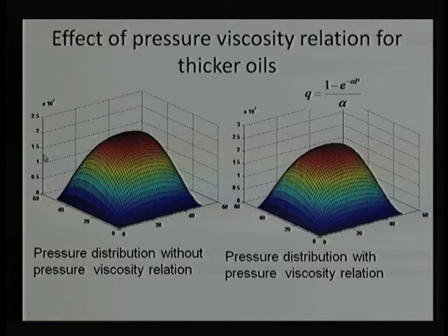In this case particularly it is 1.25 into 10 to 7 pascal, or 1.25 into 10, that means 12.5, and 10 to 6, that is a megapascal. 12.5 megapascal is the max pressure, and we are able to see there is some variation. So, from 12.5 it is maybe going to 13.5 or 13.75 megapascal. There is a change in pressure in this case.